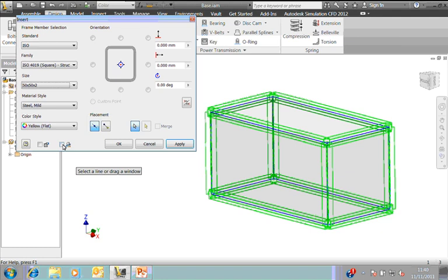The second one is relatively new. This gets the frame member's part number from the content center. Now this is actually very useful if you want to roll up standard lengths, common lengths of steel sections. So if I've got some box section, say I've got 4 of these a meter long, it'll roll these up into the parts list as 4 off a meter long, as opposed to giving these all separate part numbers, and obviously in the parts list you just have one of each. We're asked this all the time. It's quite useful to do this. I would suggest you don't use that button if you're using Inventor Professional with the item master, because that doesn't come through correctly at the moment.